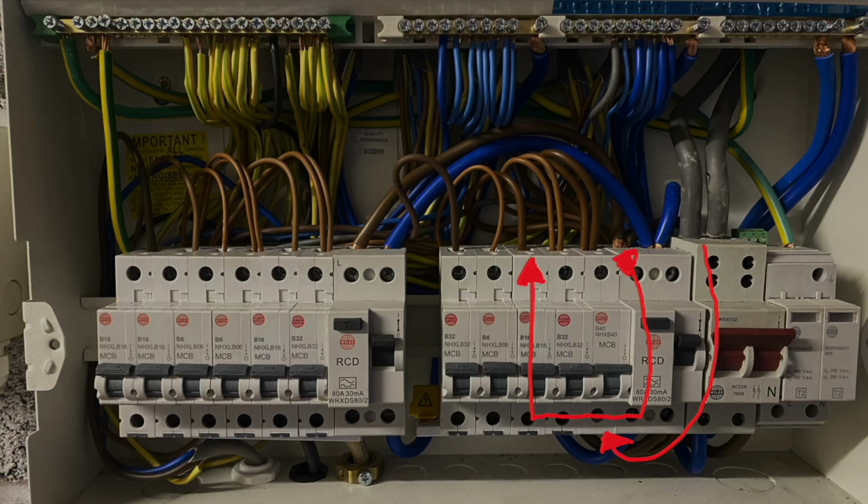But when the PV array is generating and the inverter is sending current from the inverter to the supply, it is flowing through the load terminals of the RCCB. The RCCB has clear markings showing where we should connect the load and supply terminations. So when we are feeding back towards the supply, it is going through the RCCB the wrong way. With current flowing in the opposite direction, it could render the RCCB permanently inoperable.